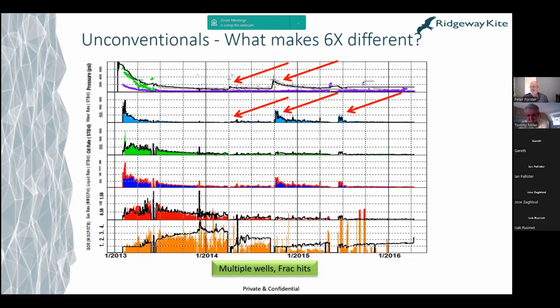So it's what's become fairly standard these days in reservoir simulation. I think it's basically an orthomin solver with a CPR preconditioning, and the CPR preconditioning uses a multigrid solver for the first stage. The complication is that we want to implement this, as you've seen, on a wide range of platforms. So it's got to be compatible with CPU, multiple CPU clusters, and GPUs and clusters of GPUs. That makes the development of the linear solver a little bit more complex, but we've designed it in such a way that it'll give you the same answer regardless of what type of platform you're running on.